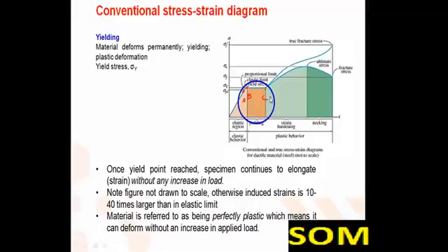The stress strain curve then has a smaller and smaller slope until at point B the curve becomes horizontal. Beginning at this point, considerable elongation occurs with no noticeable increase in the tensile force from B to C. The phenomenon is known as yielding of the material. The stress at point B is called the yield stress.